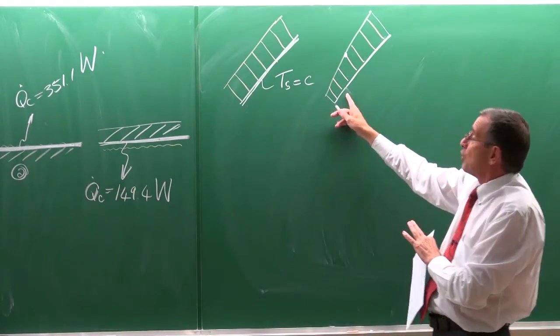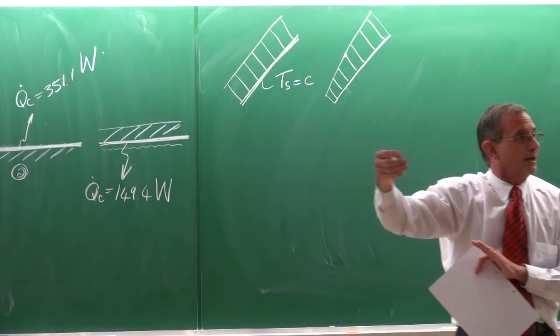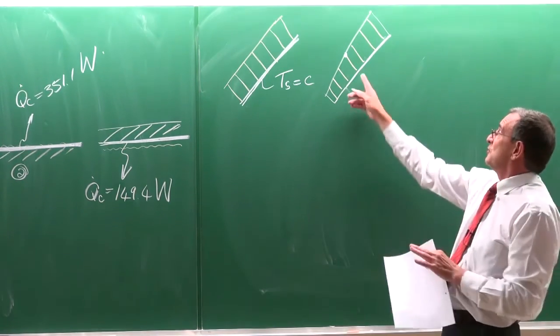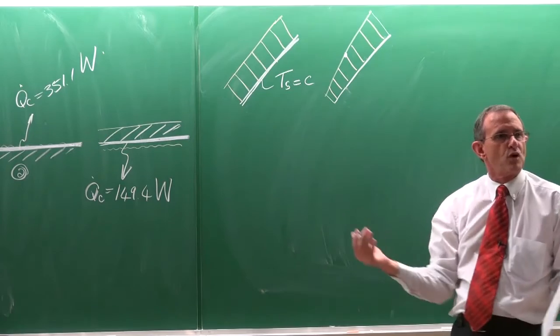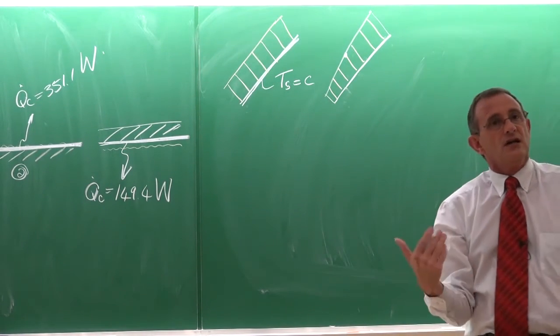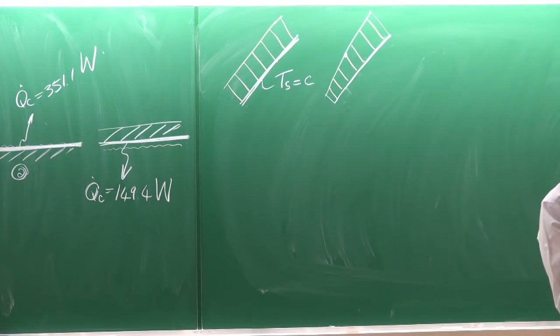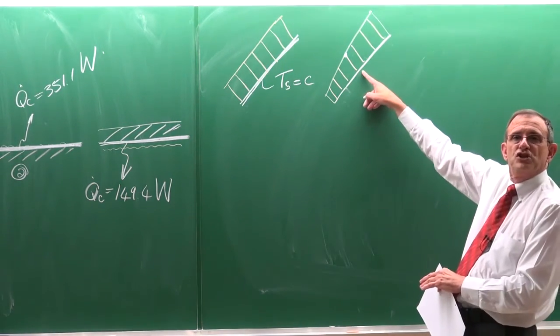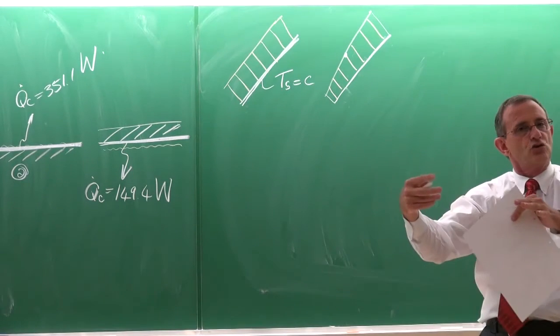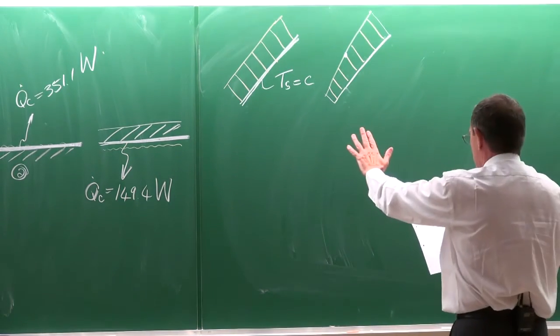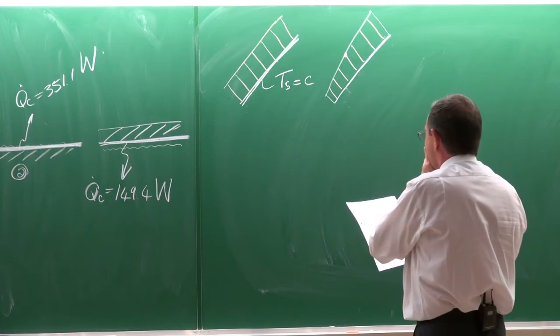But when you're given a problem of a flat plate with a heat flux of 1 kilowatt per square meter, you don't have a surface temperature, so you have a problem getting the film temperature. As we've discussed previously, you guess one and go through all the calculations. Then you calculate the temperature there, and then you correct your iteration. That is something important to remember.